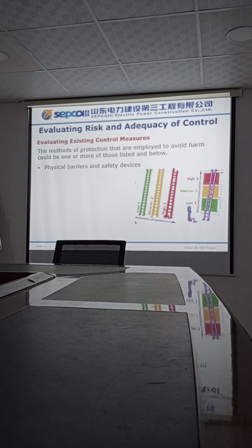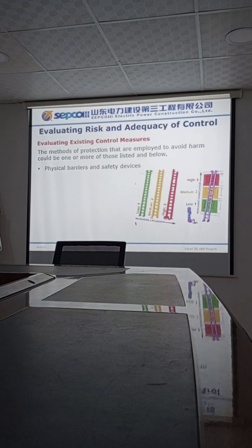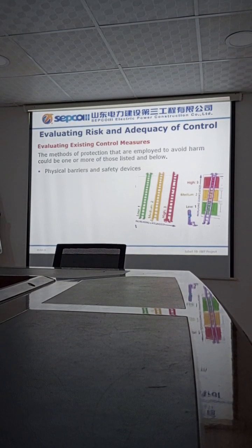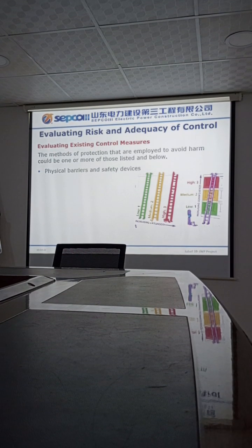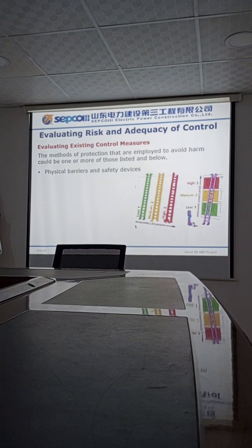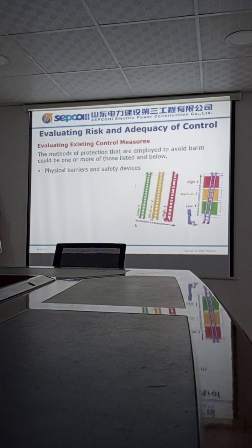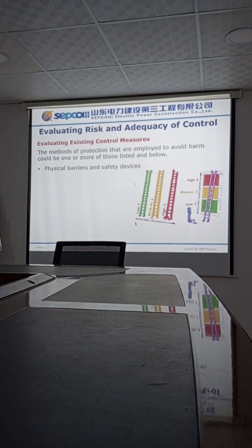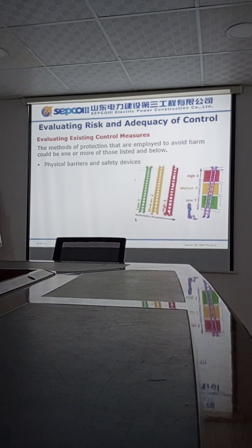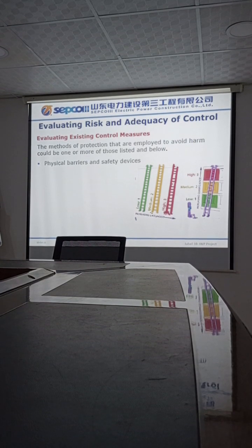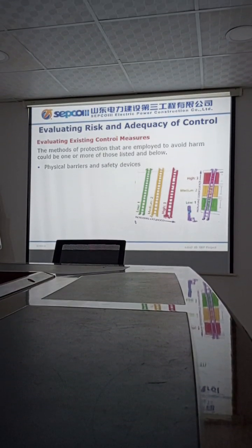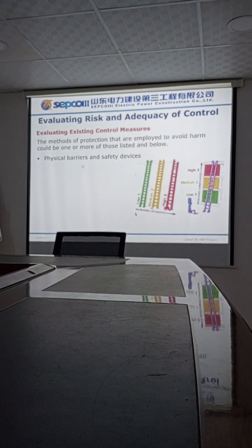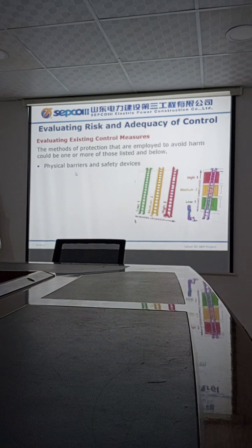Okay, you provide the roof barricade, roof and warning frame. It is okay, it can be controlled, but if the people or workers come to that, it is still possible to pull down, right? Yes, sir. Yes, you have control. It is identified. But if the guy comes there, the possibility to pull down is very high. Now we need to reduce. That's why control measures. So the barrier should be a hard barricade.